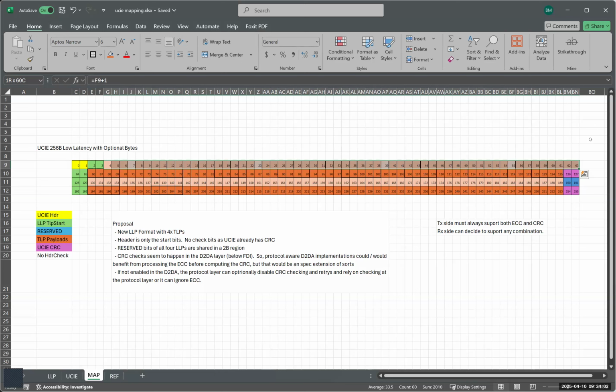So at least assuming we don't have any problems truncating the LOP and having half granule headers basically, then your actual payload size for a given LOP is the same. The only waste in the system is 16 bits of reserved, which I'm sure we'll use at some point. But there's no difference here that you would have to remap.